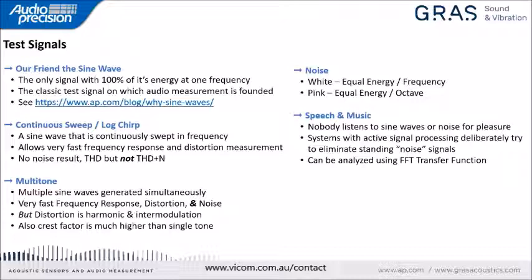And the main advantage of pink noise is if you actually look at noise measurements in the real world, the natural world does not have flat noise with frequency. The natural world is actually dominated by low frequency noise. And what you generally see is a curve where the energy is equal per octave. And if we're looking at it on a spectrum analyzer, we'd see a decrease of energy approximating 6 dB per octave.